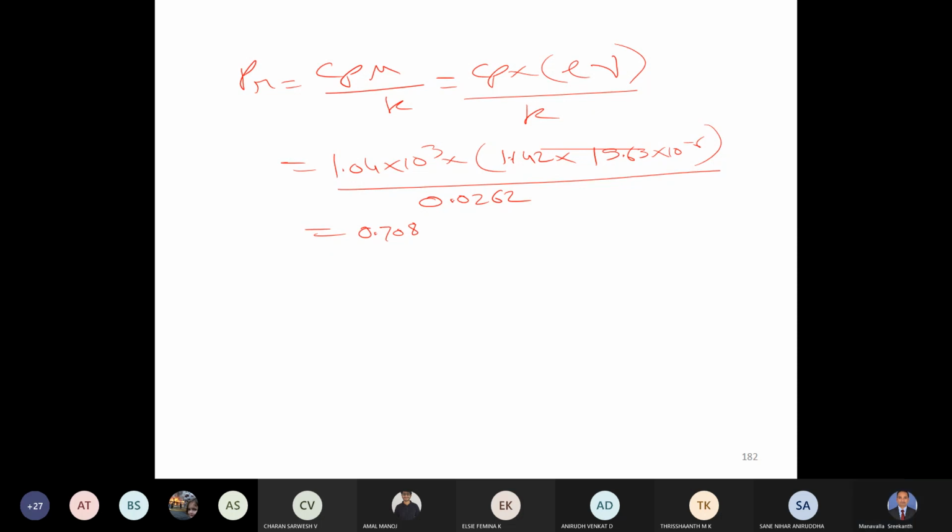Now you can see the Prandtl number value for all these gases. For air, it begins with 0.728 and goes to 0.724, so it's around 0.7. Similarly for nitrogen also around 0.7. 0.665 is the least, but it's going up to 0.79.